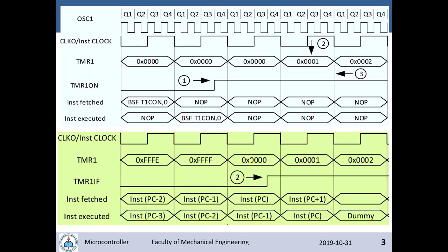Look at the timer or counter more carefully. You will see that for the system clock, 4 pulses at the crystal will create 1 pulse for the timer. We call it the timer and counter clock.